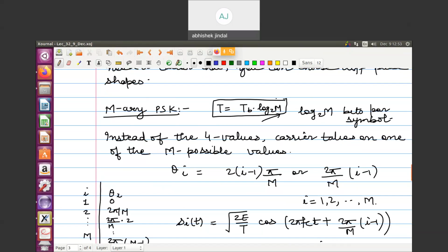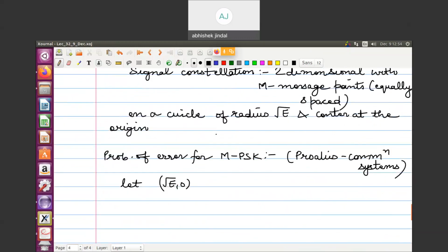The biggest impact is that if your pulse width is small, the frequency consumption or the first null bandwidth is higher. So in BPSK, the band consumption, or the first null in baseband, will come further out as compared to QPSK and MPSK, because the symbol time is increasing. If you have greater time coverage, your frequency coverage would be lesser, because the changes are not as abrupt. You should appreciate this; we will see it when we discuss bandwidth efficiency.